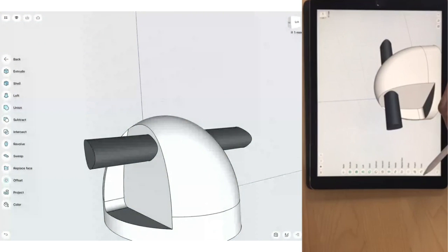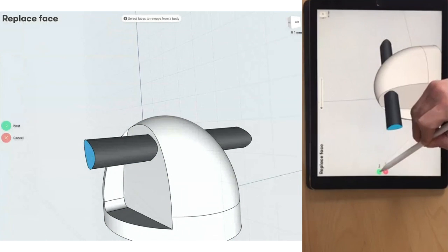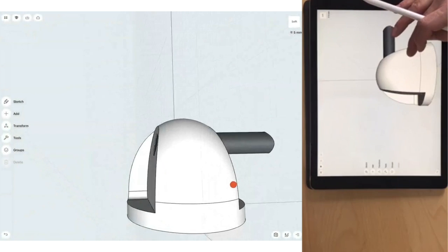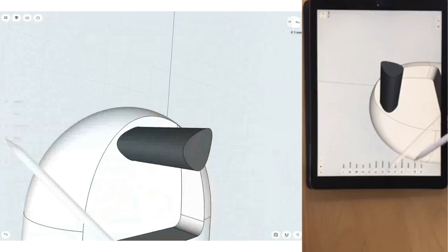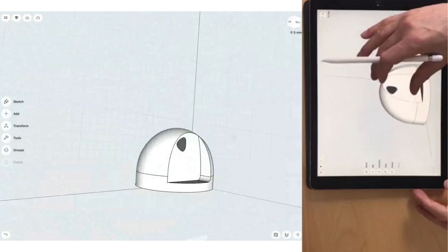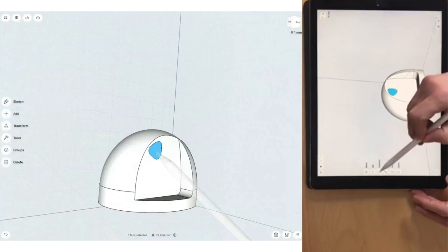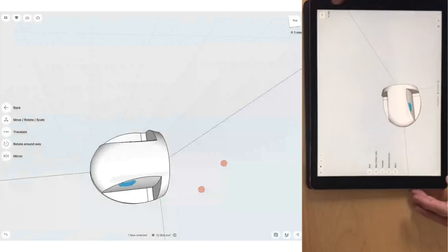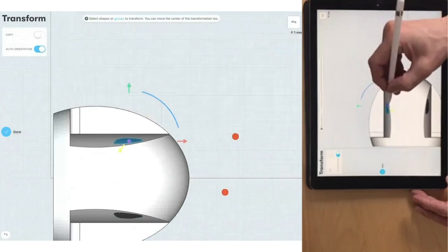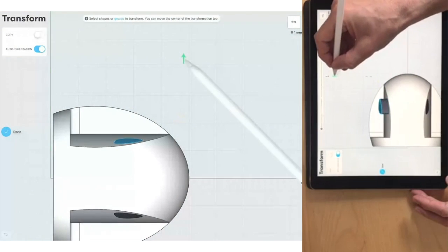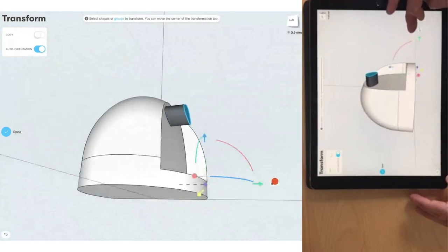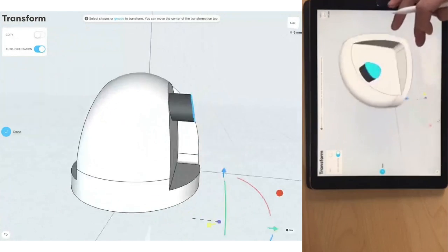So tool and replace face. Let's check something out. This face with this face. Oh, you see that? It moved it to there and adjusted that face. So no trimming. Autodesk, take that. There. Awesome. And we might only have to move this face then out. Let's go to the top view, move. I want to go to the grid, and then we stretch this one out. By snapping to the grid, you can see the move widget got oriented, so it's horizontal.